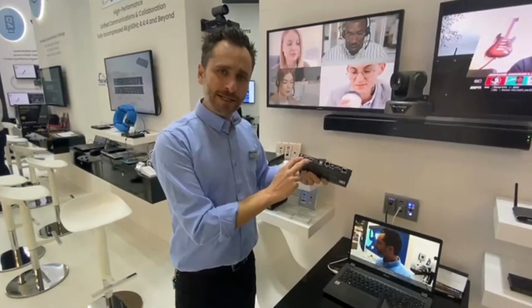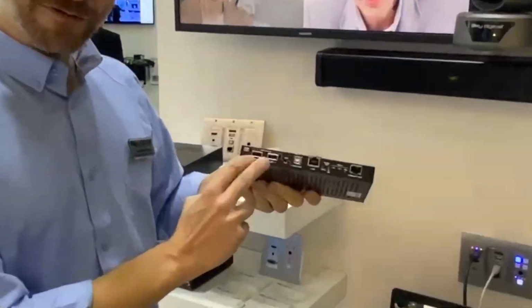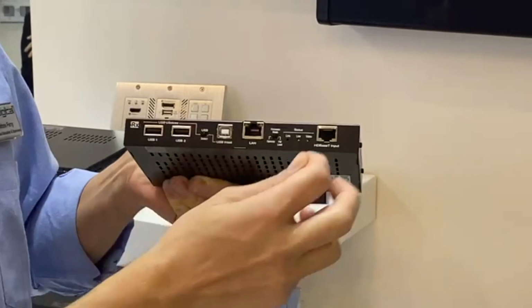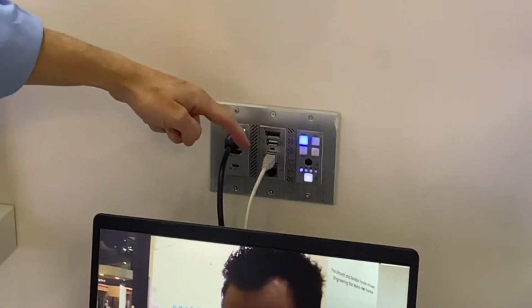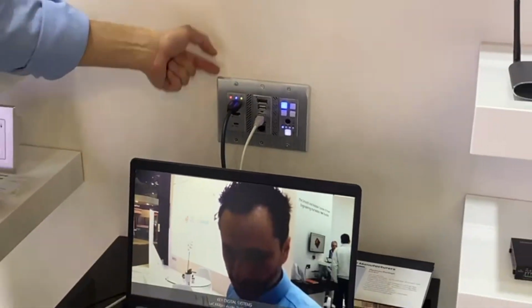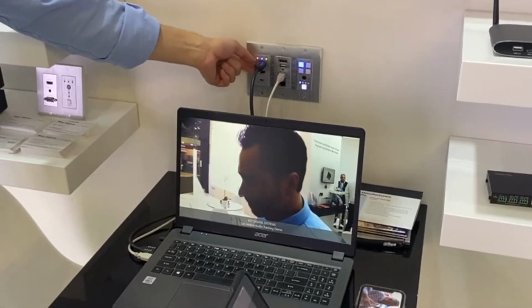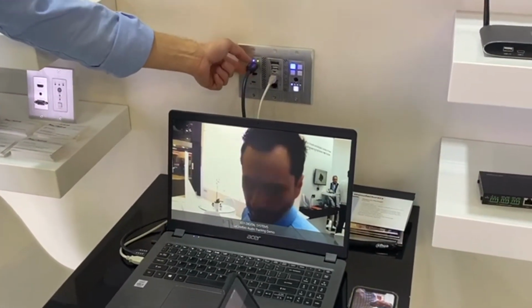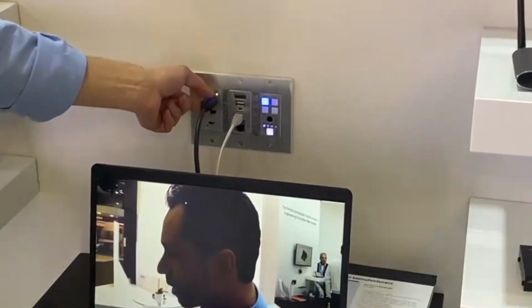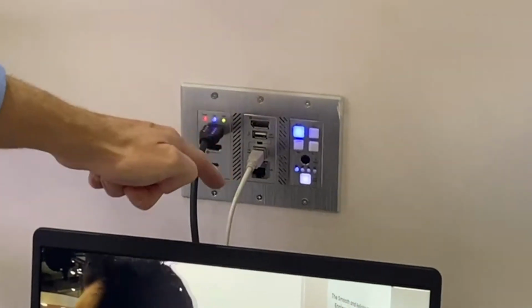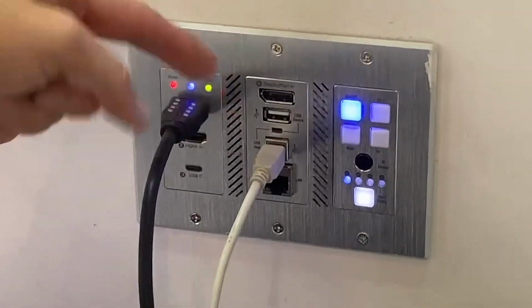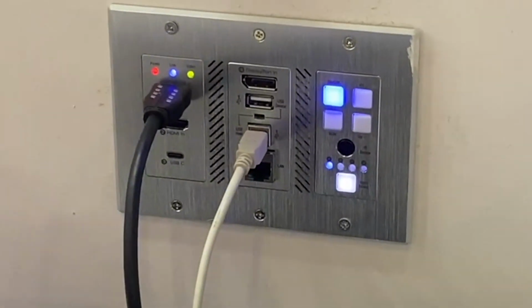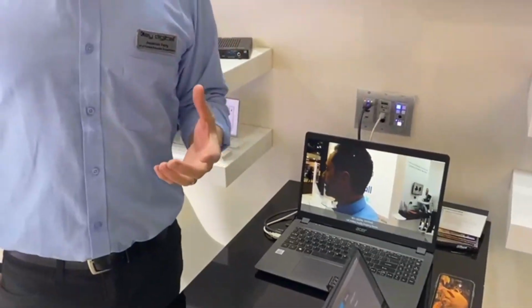Those are most likely connected into our HDBaseT receiver, and then through HDBaseT, it's going to go backward to the presenter, where that presenter is able to connect HDMI, AV, or USB-C or DisplayPort for sending their presentation content to the screen, or connecting USB. And now this camera, this webcam, go into the laptop computer for those bring your own meeting type applications.